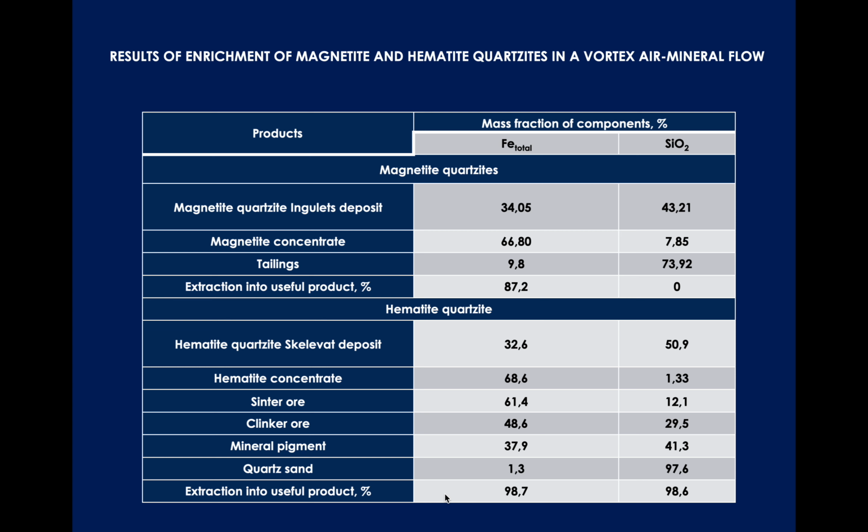destruction by impact forms cube-shaped particles. Lamellar hematite splits along rhombohedral cleavage, acquires an isometric shape and, as a result of gravitational differentiation in a vortex air mineral flow, is unloaded into an iron ore concentrate receiver along with magnetite. In this case, tabular and lamellar silicate individuals are removed from the working chamber into a bag filter.